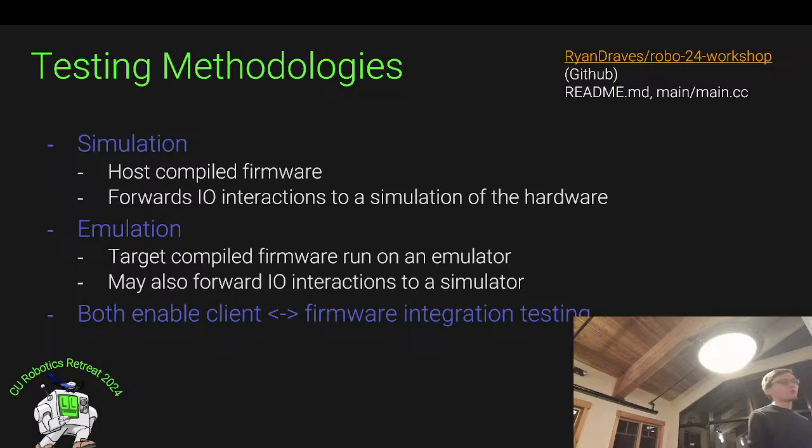Typically, you would also forward your I/O interactions to some sort of alongside simulation of the hardware. So I could have the emulated hardware on one side, and then my simulated firmware on the other side. And I could run some sort of client test and say, end-to-end, I'm going to send a client request to my host compiled firmware. It's going to go and pretend to interact with some piece of hardware, and I'm going to read out that hardware and make sure it did the right thing, right?